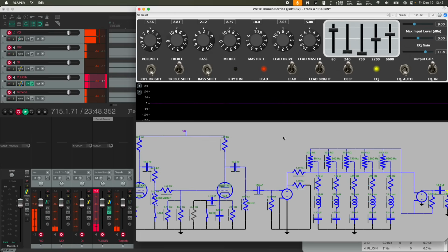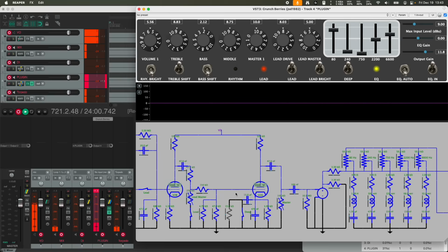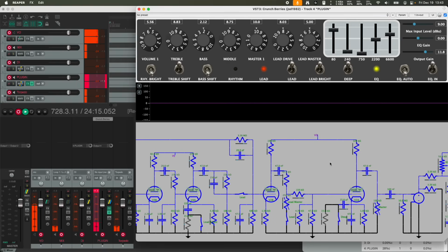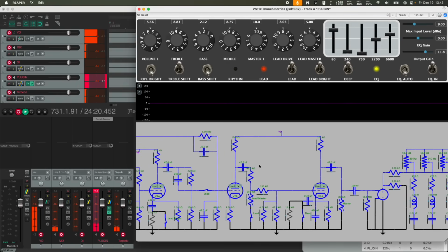I have actually expressed the circuit in the source code itself. So I could change the topology of the circuit at a whim. I could add a resistor in here, or add a capacitor in here, or put a capacitor in here in parallel. It's just a simple change at the code level. And then what happens is the C++ compiler is really doing a lot of heavy lifting here and optimizing the stuff that actually simulates the circuit. So it has all the knowledge of all the components, and it can run compile time algorithms to simplify or optimize the code to simulate this circuit.